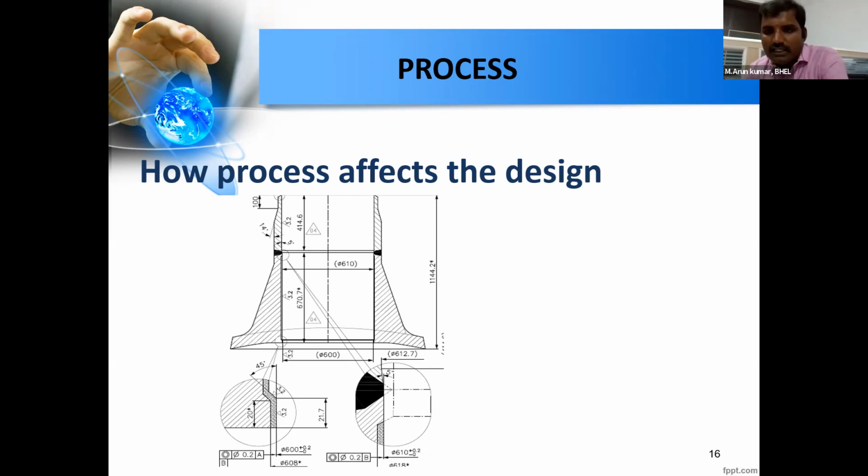In the region wherever they have done some rework, it is not noticed while checking the thickness by any relative method to find out the thickness. So what happened is, there we got many cracks and indications. Then we found out that we have to give some more cushion for the welders or for the process. Then we have increased this cladding thickness, and we have remodified our design.